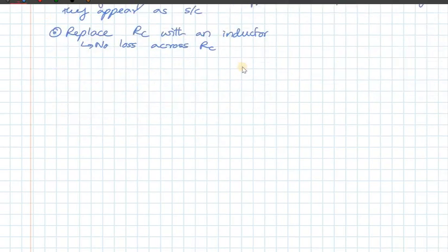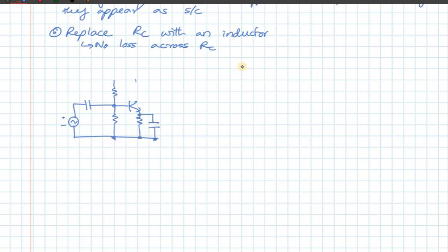Let's assume we have biasing that, and the circuit is connected to the source through a resistor, the capacitor, like before. And you have the first stage. Maybe this is a common emitter amplifier configuration with an emitter resistor. Now instead of RC, I'm going to put an inductor, right? So this is an inductor. Inductor is connected to VCC. So this is my first stage.